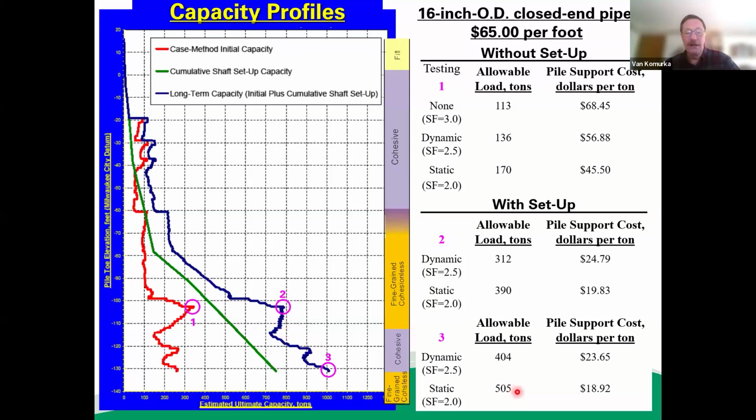So even though this is now 1,010 ultimate tons, and you get these huge allowable loads, because of the extra length invested to go from 0.2 to 0.3, these two numbers are within accuracy virtually identical, and these two. So you could look at this and make an economic decision, make a cost decision, and say it's not worth going after these allowable loads. They're no more cost effective.